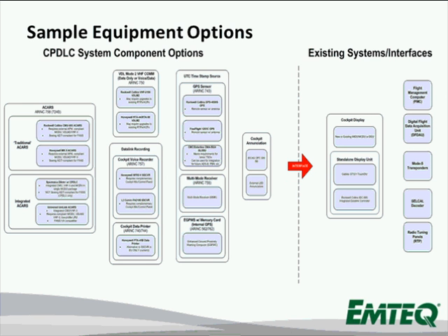This chart just shows what some of those systems are. I know it's very small print, but on the left-hand side we start out with the ARINC 758 or 724B ACARS. There are traditional ACARS systems, like your Rockwell Collins CMU-900 ACARS or your Honeywell Mark II ACARS. They require an external aircraft personality module, an MCDU, a separate VHF communication system, and then there are integrated ACARS systems